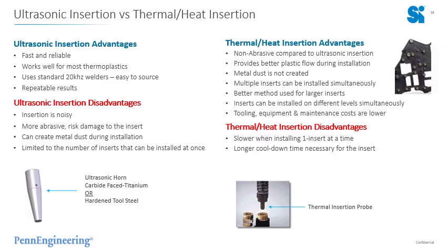So now the advantages to thermal heat insertion. It's not abrasive, and provides better plastic flow around the insert body. There's no metal dust created. Multiple inserts can be installed simultaneously. It's a better method for much larger inserts. And so it's possible to purchase tooling where your inserts can be installed on different levels simultaneously.